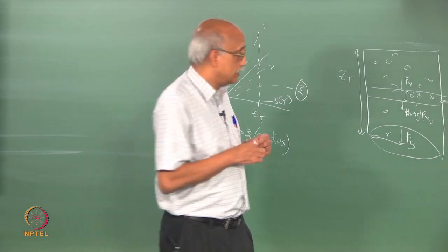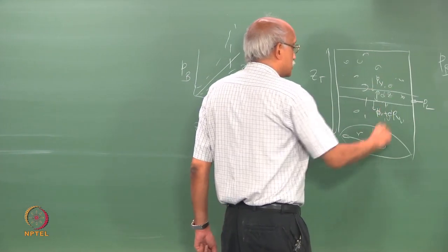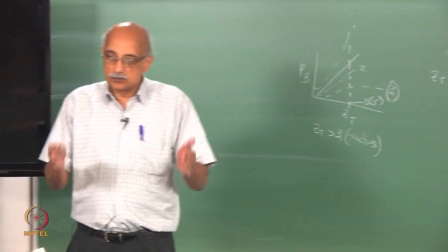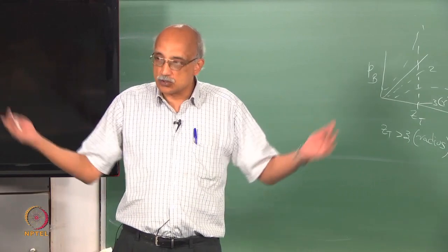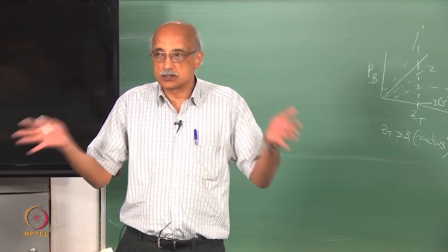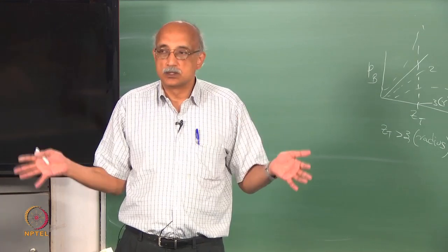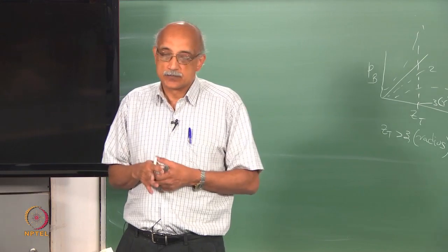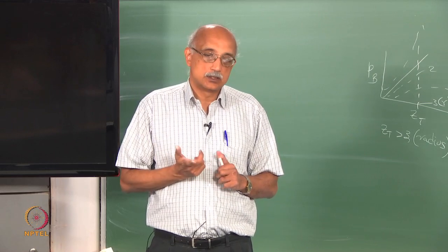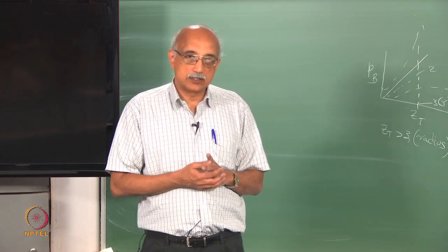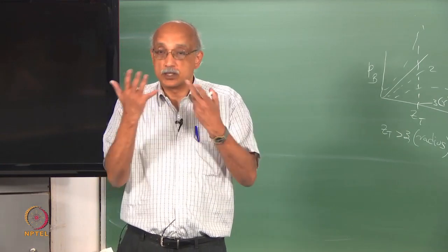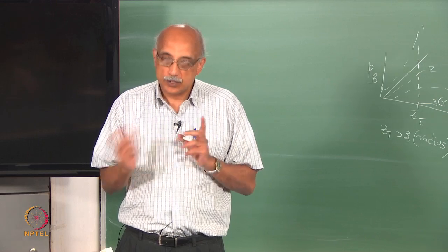The other type is where initially the discharge starts in the center and then slowly forms like a V and starts drawing in materials from the sides, so that the discharge starts in the middle and then slowly expands to include the other areas of the bin as well. The latter is actually more likely to happen. It is very rare that you see this mass discharge. The other type is called the tunnel discharge or conical discharge, and that is more likely to happen.